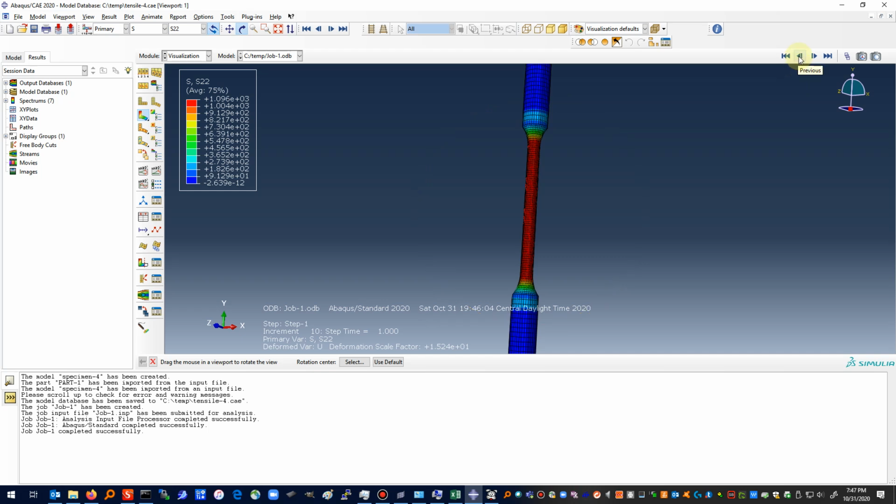So if we take this and go back to time step 1, which would be a 0.1 in time, then here we have 109.6 for our stress that's in the upper end of the red zone. 109.6 megapascal. So that's a pretty reasonable stress for a tensile specimen. Of course, this being a purely elastic analysis, we can keep applying stresses until whatever number we want to get. A real material will fail or yield before it gets to any particular value.